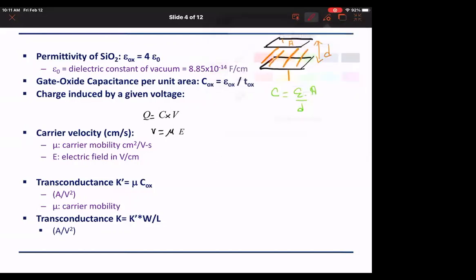One thing that we need to note in the MOSFET is that, given that this is the metal gate, it has some silicon dioxide here, and the thickness of the silicon dioxide is Tox. And if I want to measure the capacitance at the gate, that is responsible for the charge accumulation in the channel, because what does the capacitor result in?